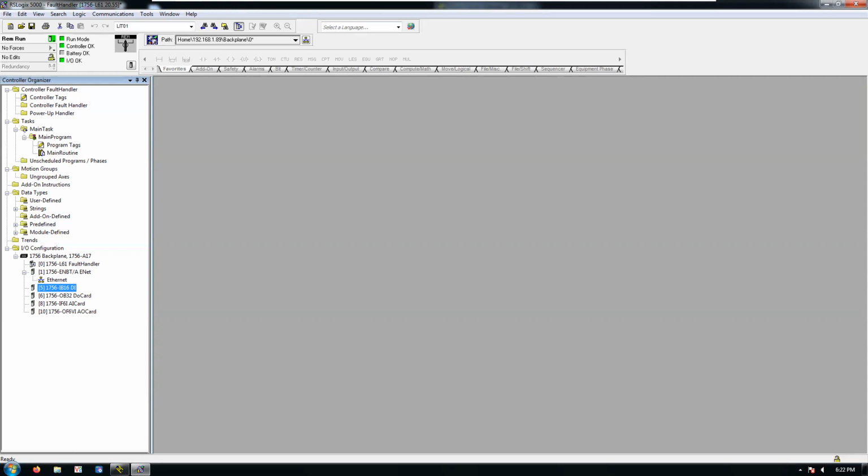So they can't be cleared, and sometimes they'll actually require a download to fix. So if you corrupt your processor, obviously it's going to stop running and you'll have to download a new copy of the code or set up automatic recovery through an SD card if you have that.